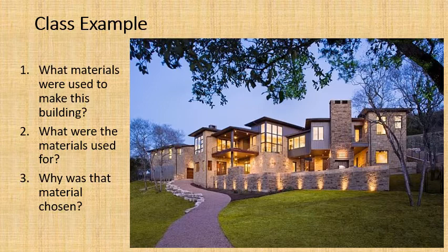That means if I had a brick of concrete and I had a clamp on either end, I could pull the brick apart. I could stretch it and it would crack very quickly. So they needed a material here where you've got this cantilever where it's leaning over on a big beam. They needed a material that had good tensile strength, and that's why they used wood. If they had used concrete, it would have broken. And with every material that's used throughout the house, there is a reason why they chose that material. The properties of that material matched the requirements of that component of the building. So that's building materials and testing.